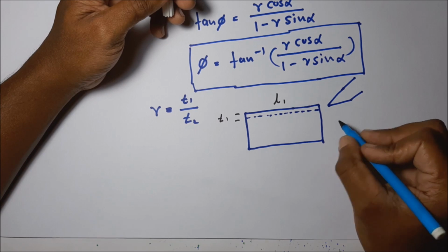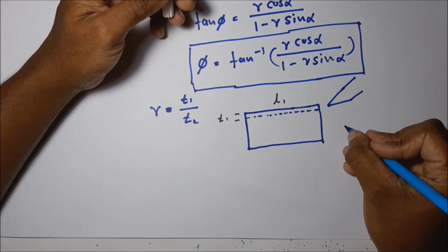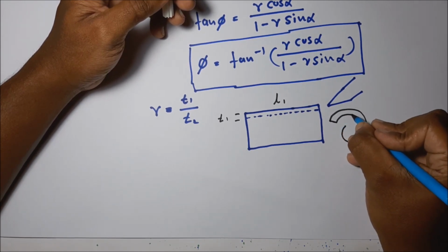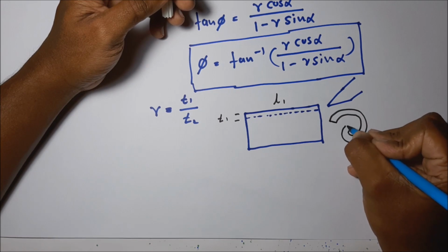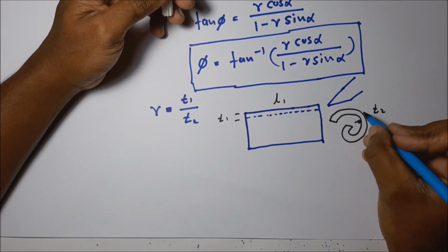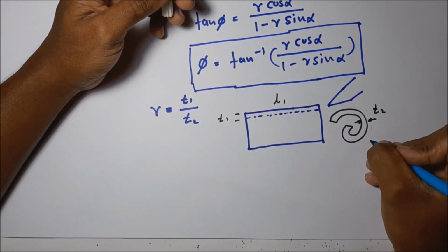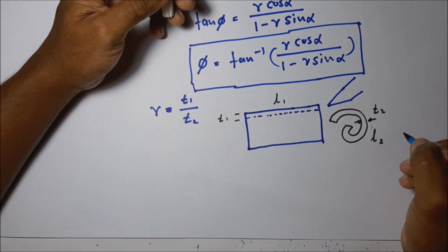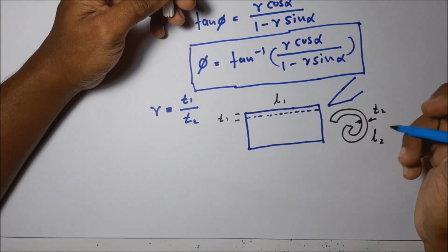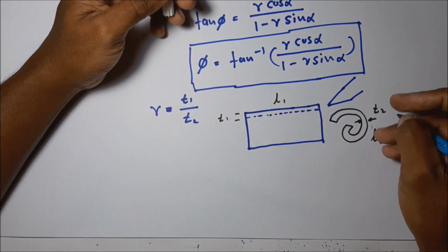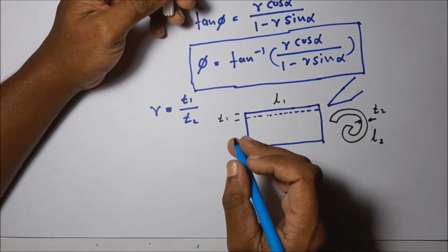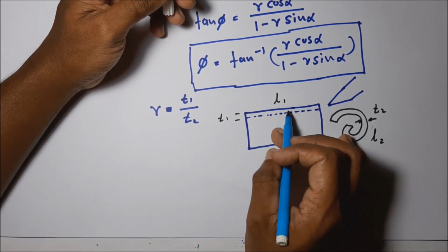Its original thickness varies. So let's take it forms this kind of coil shape. Then in this situation its thickness is T2, and its curved length, let's take it as L2. We are assuming the deformation perpendicular to this surface is 0, so that the volume of these two should be equal before and after it is removed from the work surface.